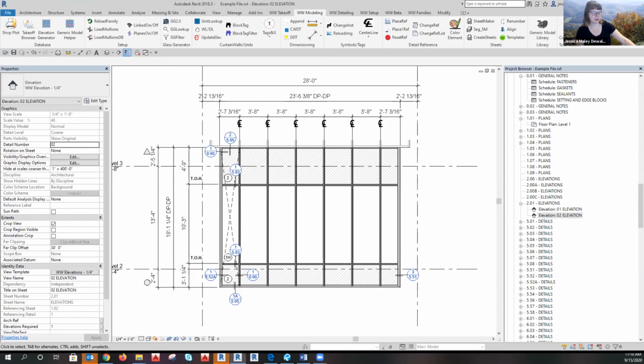And I think Katan mentioned too that after you finished making this elevation, you could save the whole thing as a system. If you have the same setup for other places on the building, you don't have to manually enter each of the mullions again, right? Yeah, you can save a system. The thing is that with the wireframe models, saving the system doesn't work quite as well as if you're going from the sales model or an architect's model. But you can always save the system in the elevation generator and it will remember some things.